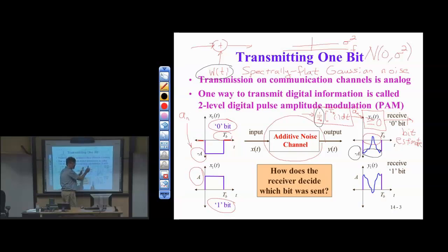So I'm really using it as an FIR filter. The impulse response is finite in length and duration, and not the usual continuous output of the integrator, which you just saw in homework. So in this case, we're using it in a way that makes it BIBO stable, because we're only applying the integration over a finite period of time and then restarting the integration with the next symbol time.